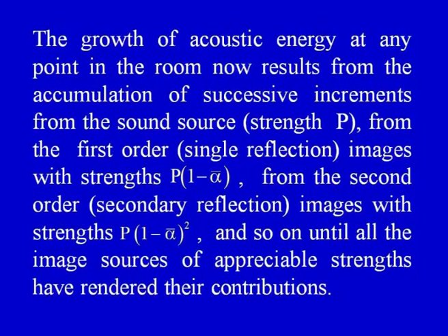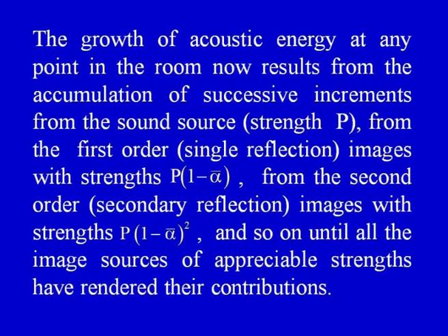The growth of acoustic energy at any point in the room now results from the accumulation of successive increments from the sound source, say of strength P, from the first order, that is single reflection images with a strength P into 1 minus alpha bar, from the second order, that is secondary reflection images with strength P into the square of 1 minus alpha bar, and so on until all the image sources of appreciable strengths have rendered their contribution.